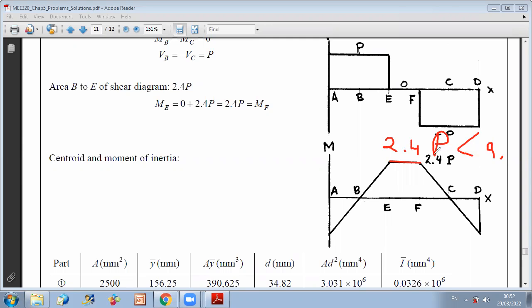So when we did the analysis of maximum positive moment, we found two values for this maximum. We select the smallest, which corresponds here to 9 point something. So now you can find the minimal value of P to satisfy the first condition, that you are not exceeding the allowable stress of tension and compression for a positive bending moment.